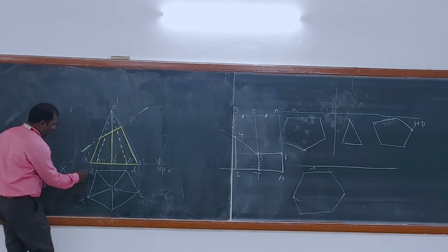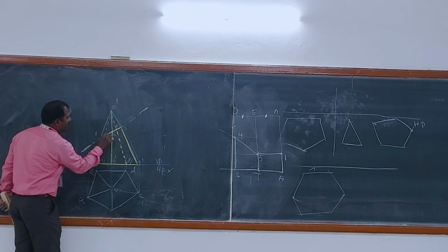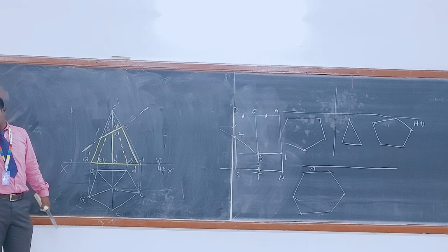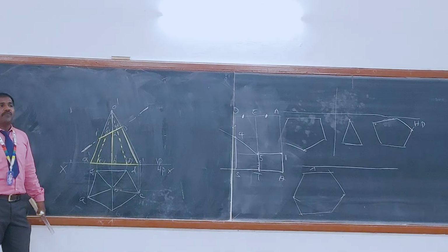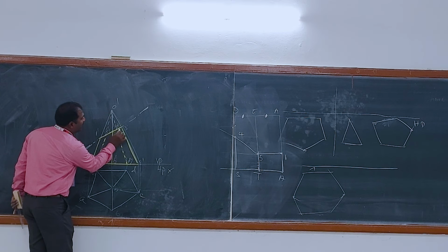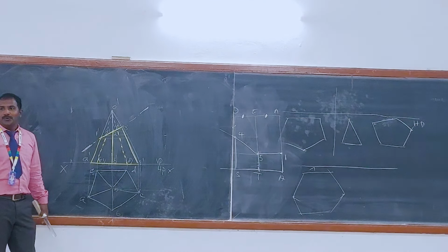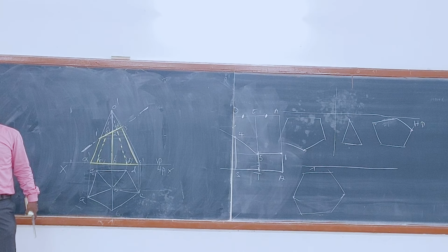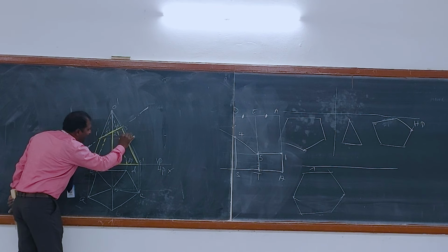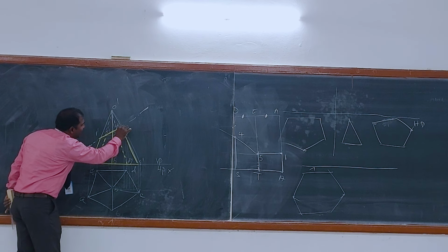First I will give the names: 1, 2, 3, then the one at the back 4, this is 5, all with dashes. Understood? Names should not be given for the hidden ones now; later we give them at the back. Clear? We have 5 names and all 5 are fake, not true slant edges. So we have to draw a vertical line, one horizontal line, second, third, fourth, fifth horizontal line. 5 lines you have to draw to the true slant edge. From here we draw vertical lines for all: for the first slant edge a vertical line, second, third, fourth, and fifth slant edge a vertical line.